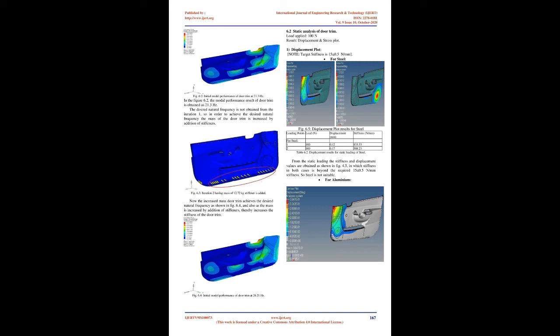5.3 1D and 2D element information used in door trim modeling. 1. Rigid body element, 2D element. Properties of rigid elements. A. A rigid element is a 1D element, used to represent bolt connections and connect different components. B. A rigid element has 6 degrees of freedom, which can be released as per the requirement.